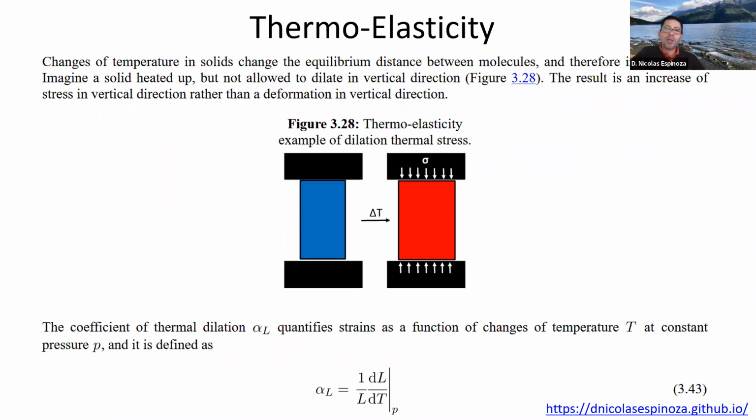Well, going into rough numbers, it's kind of difficult, but we really want to avoid very, very sharp changes, like more than a 50 degree C change, I would say, in general. But that rule might change from place to place. Yeah. And how fast this change occurs, is that also an important factor? Meaning a 50 degrees Celsius change over a year may be okay, but a 50 degrees Celsius change in a day is definitely going to be bad.